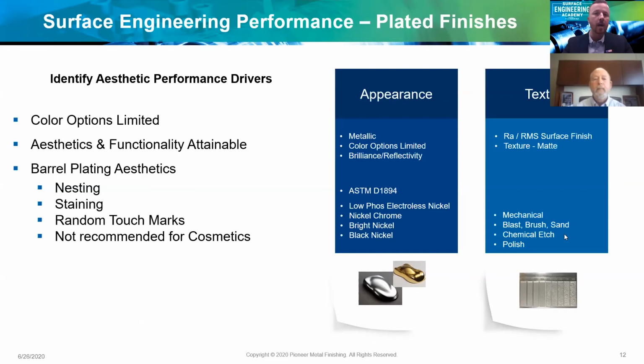So any sort of dyeing or colorant along with a plating, unless it's electro-deposited with the plating, is going to be more superficial or surface-oriented and not as durable or wear scratch resistant. So keep that in mind. And that's oftentimes why you see plated finishes are going to be metallic in nature. That's just the nature of it.